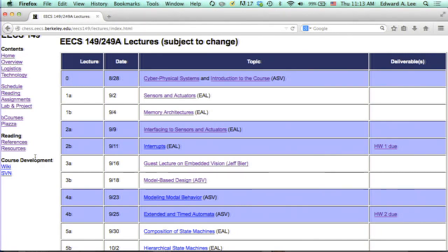The second level, of course, is much more familiar to most people, which is where you're interacting through an operating system with the hardware. And there, the twist in embedded systems is that you care about the timing of things in a much deeper and more integrated way than you do with general-purpose computing, where timing is just a performance metric. In the case of many embedded system applications, timing is a correctness criterion, not just a performance metric.